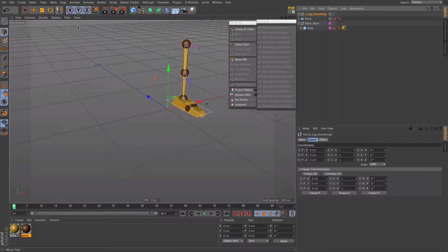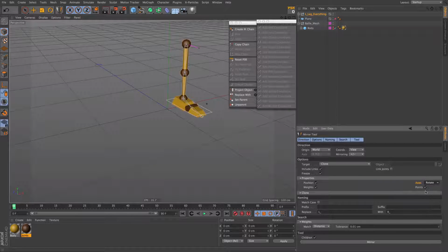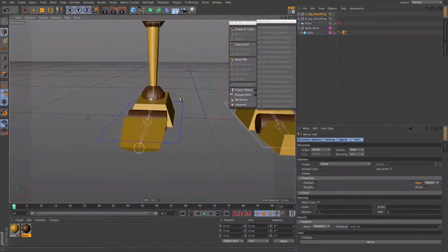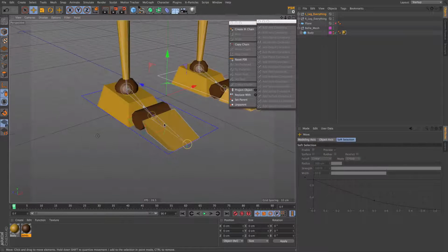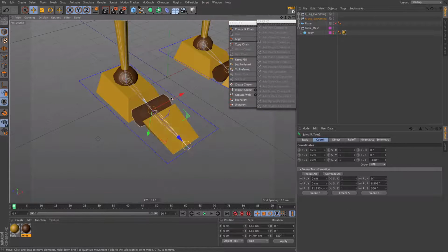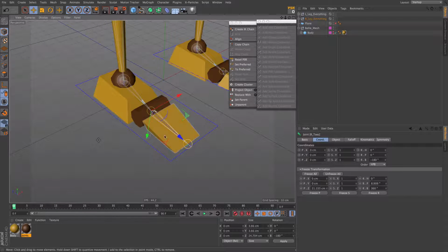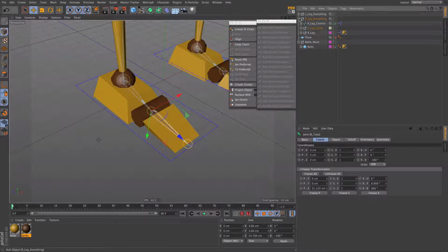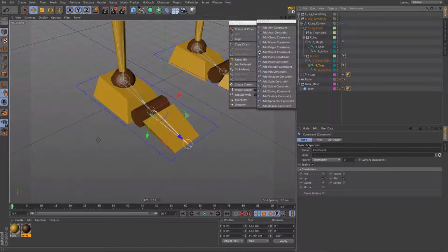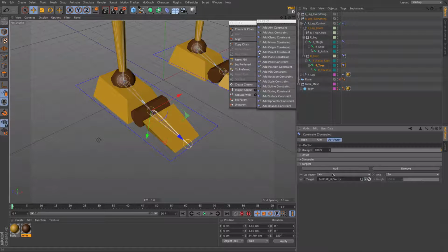Let's bring our mirror tool again. And I think the rotate does a pretty good job most of the time. Let's use this. We can see, of course, in this particular case, it's not mirrored properly. This is flipped, but let's take a look inside the rig. Let's go to the toes, and on the constraint here, let's change the up vector from x minus to x plus.